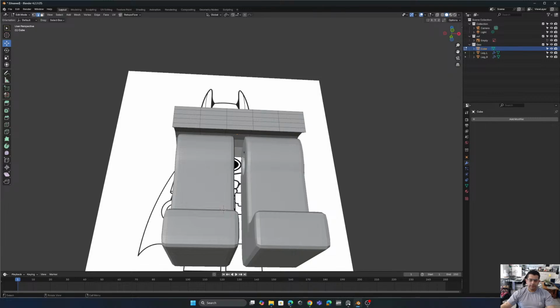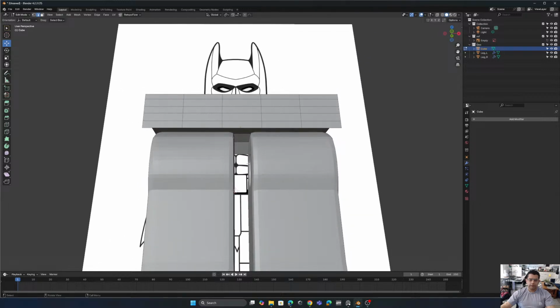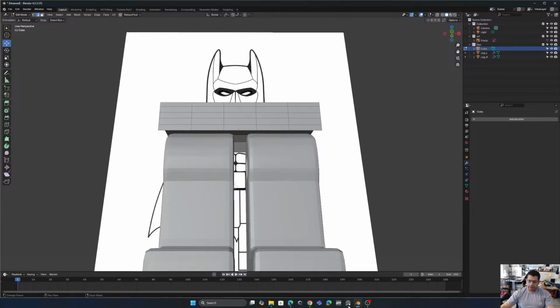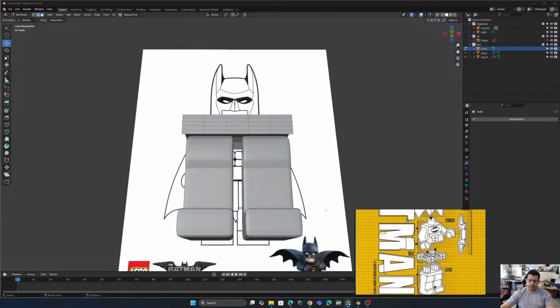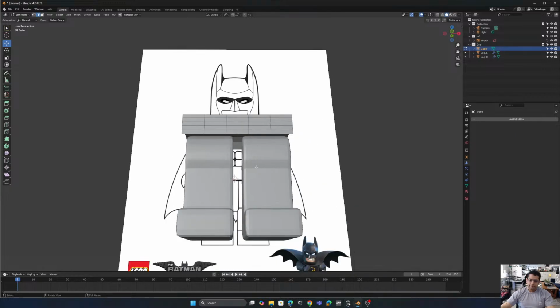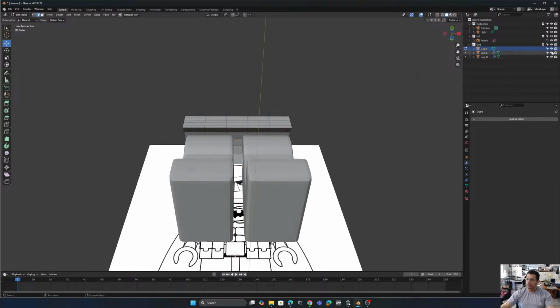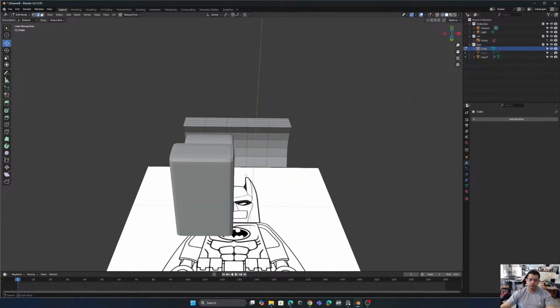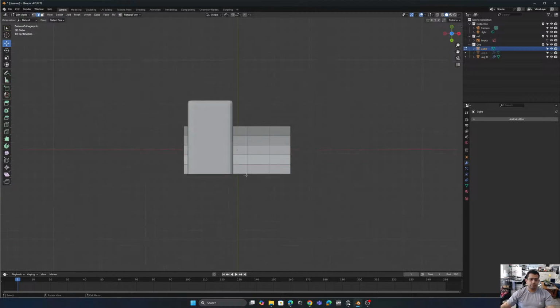Now I need to create this circular part that is gonna be in the middle of the legs, that actually is the piece that's gonna hold them. So this part. Let's try to do that. Now I'm gonna select these faces. I'm gonna turn off one of the legs just to have a better view. I'm gonna press 7, that is gonna send me to the top view, and then 9 in the numpad to see the bottom.